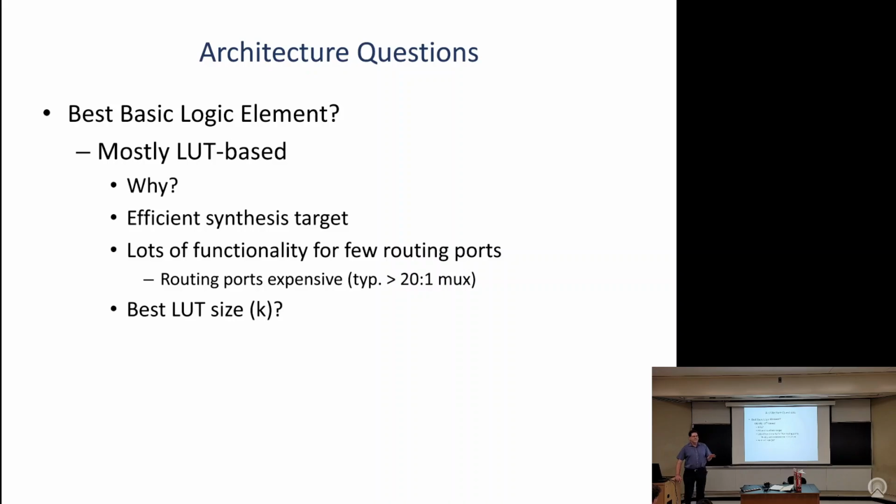Yeah, so I'm going to summarize that. We get more stuff per LUT, which is good. We get fewer of them in series on the critical path, so that's good. Because we need fewer LUTs, we wind up with fewer things to hook up to the routing. That actually saves us routing area because we can just implement the whole circuit with a smaller number of blocks. Each block is more complicated, but we need fewer of them. That's all good for area.